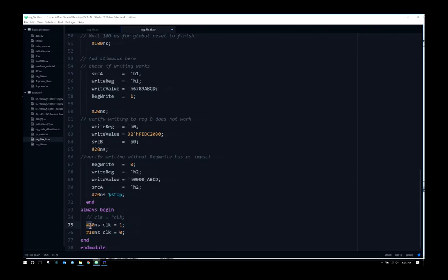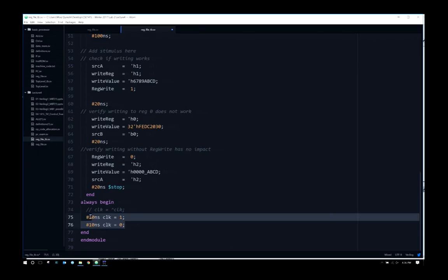So for this, you have 10 nanoseconds asserted, 10 nanoseconds deasserted. So that means you have a 20 nanosecond period. When you're doing a simulation in ModelSim, it's just like an ideal case. It's not even checking to see if your code is synthesizable. It's just assuming that your processor or your design can be made magically and run without any timing constraint.